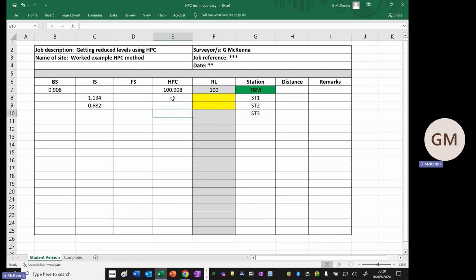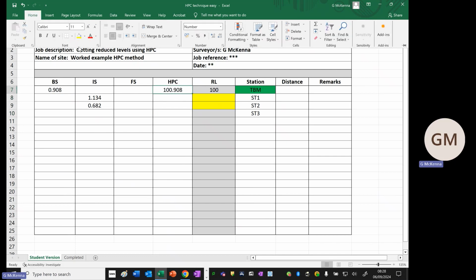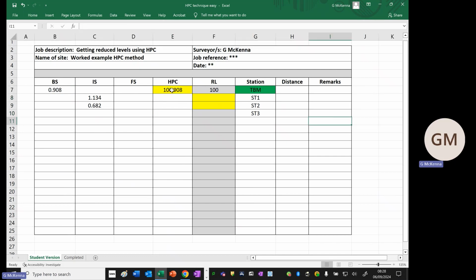So the height of my instrument here, I'm just going to fill this in yellow. You don't, of course, do this in real life, but the yellow is just the measurements you're completing in the construction office, which can be differentiated from your raw data that you've gathered out on a construction site. It might be useful, after you've taken your raw data, to use company policy to back that up, maybe take a photocopy or a picture or whatnot. And of course, there are checks to do, which we're not going to talk about in this sample video here.